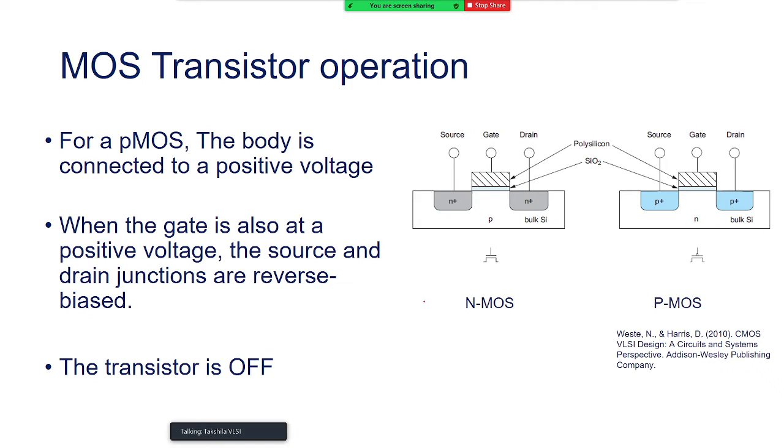So that was there. Let us understand the same working principle for the PMOS transistor. So body, let us say it is tied to logic 1, highest potential in the circuit. Always remember that for the NMOS, where we tie the body, lowest potential, logic 0. For the PMOS, we tie the body, that is N-well, to the highest potential in the circuit, that is logic 1 or VDD, right? So now if I apply a gate voltage,